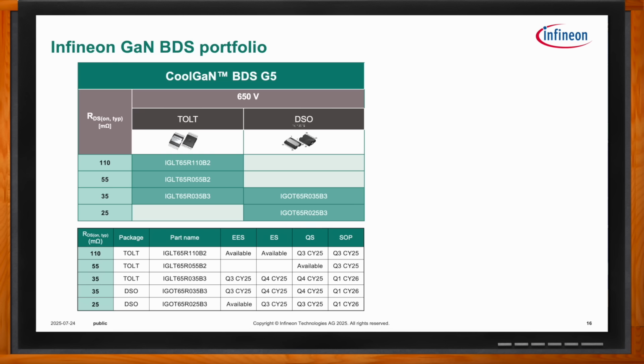With a traditional package like the through-hole TO247 you mentioned, they're legacy packages that have been used for decades, and customers like them. They're familiar with it, they're happy with it, but they just have too much package inductance to really effectively take advantage of the capability of GaN. They make it difficult to use and difficult to drive. You end up with ringing and overshoot and EMI problems.